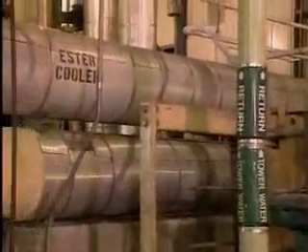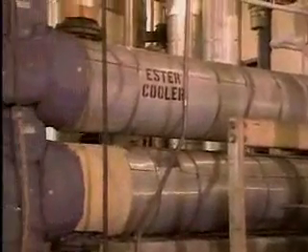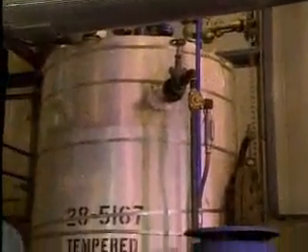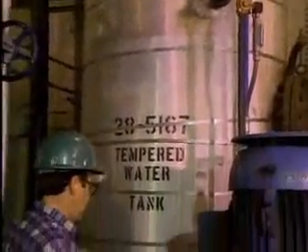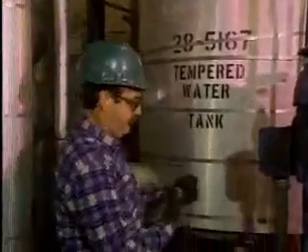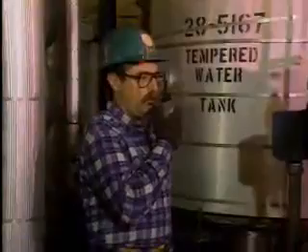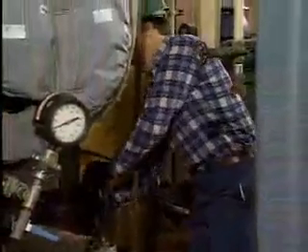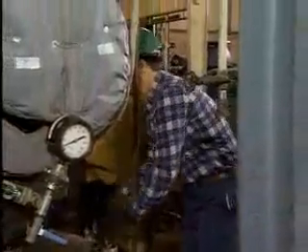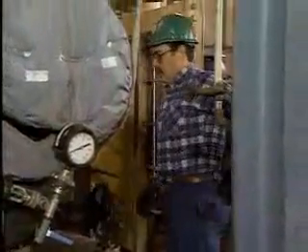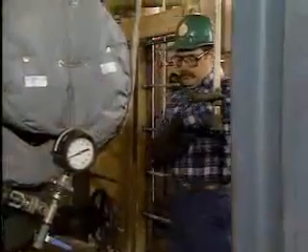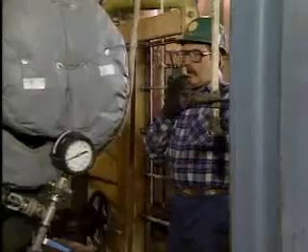Any air that is trapped on the shell side escapes through the open vent valve. As the shell side of the heat exchanger fills, the operator listens for air escaping. When the shell side is completely filled, he calls the control room and has them shut the vent valve. Then the operator opens the shell side inlet valve the rest of the way. At that point, he informs the control room that the shell side is lined up and that they can establish the proper flow rate through the shell.